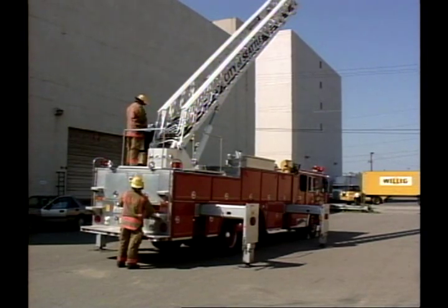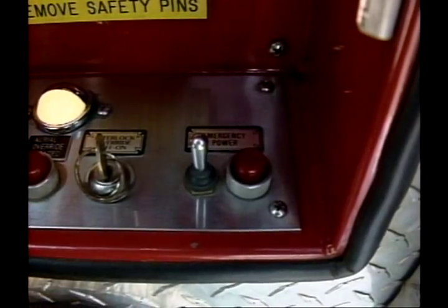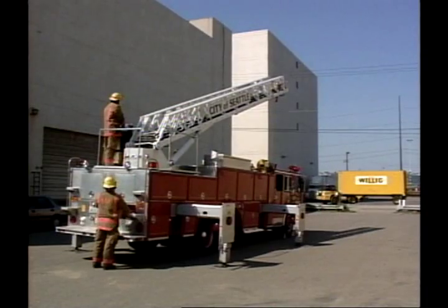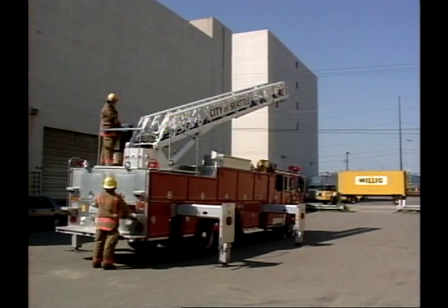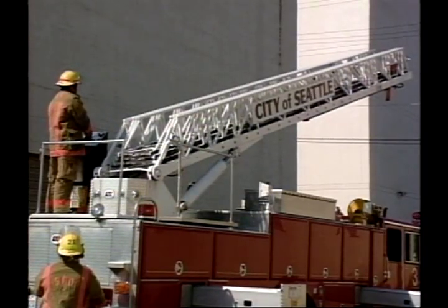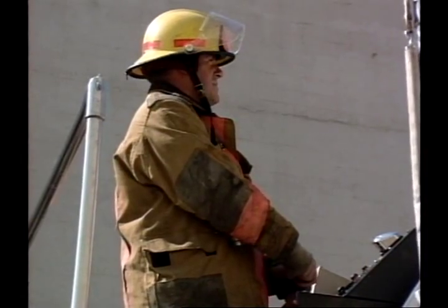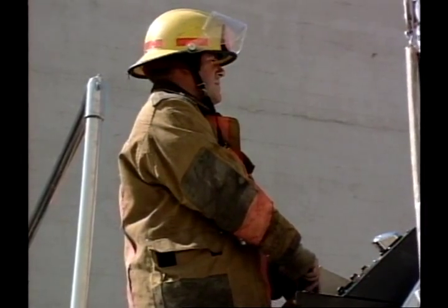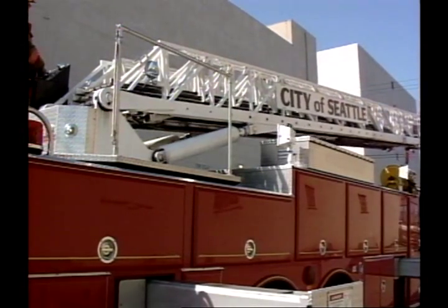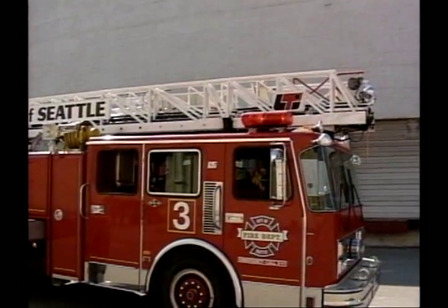All apparatus manufacturers provide an auxiliary hydraulic pump to use in the event of a main hydraulic pump failure. This smaller pump is capable of all the motions of the larger pump, but it operates at a slower speed. Because the auxiliary pump is not designed to be used for long periods of time, use it only to bed the aerial device if the main pump fails. The rule of thumb for using the auxiliary pump is to operate it for 1 minute, let it rest for a minute, then operate it again for a minute, and so on until the aerial is bedded.